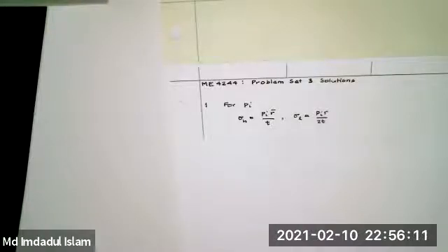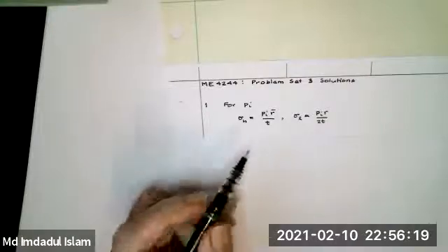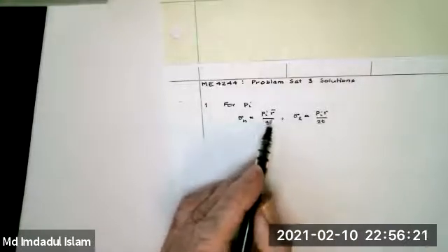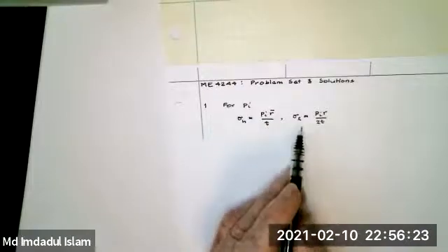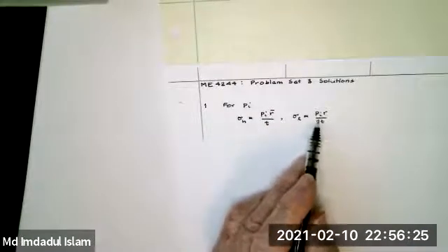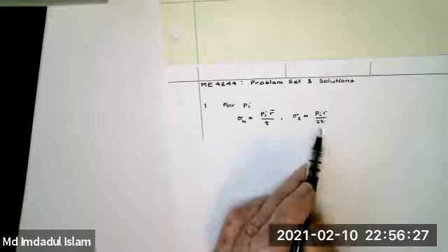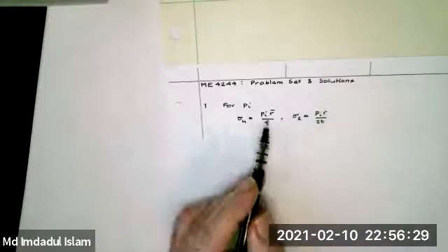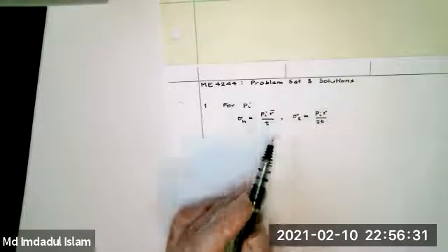For a cylindrical pressure vessel, you get about twice the stress in the hoop direction as in the longitudinal direction. These are the two formulas I mentioned briefly. This is the Shigley formula, PI R bar over T, and the longitudinal stress is the internal pressure times R over 2T. R bar is the mean radius, so it's R plus T over 2.